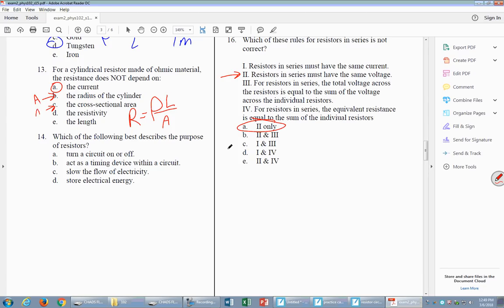This is also A, this is rho, and then this is the length L. So it's dependent upon all of those things, but it's not dependent upon the current. Now some devices, or if you put too much current in some devices, then they will no longer be ohmic. That means that their resistance will change. But that's when they're being used improperly or when they're not ohmic devices, like a diode is a non-ohmic device.